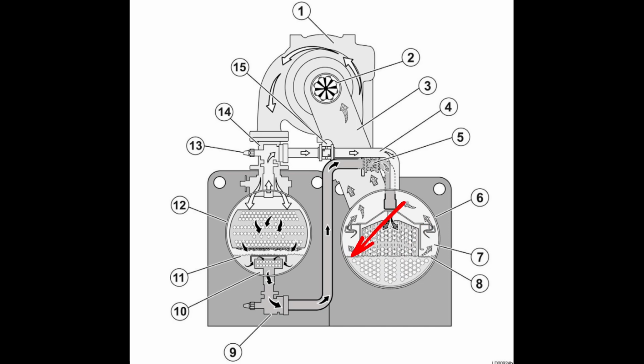Being a hybrid, if this was a true falling film, then the entire section of tubes would strictly be getting the misting, and just a small amount of liquid might be accumulating in the bottom. But typically, with a true falling film, you will have no or next to no standing liquid refrigerant in the evaporator at all, which, at the same tonnage, requires a lot more evaporator to move the same amount of heat.